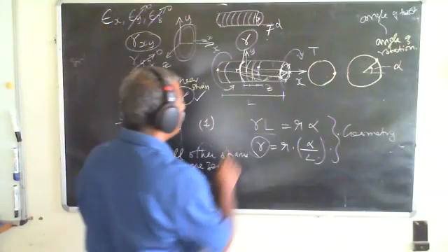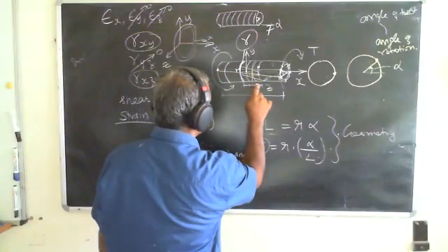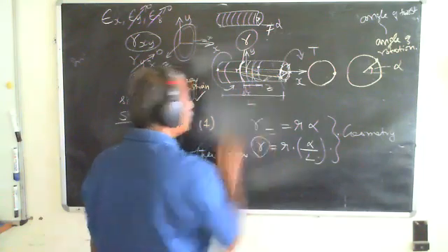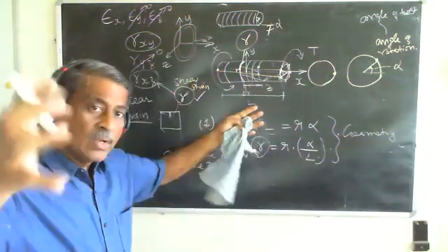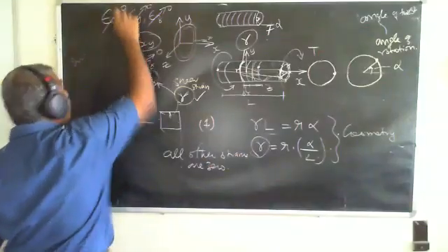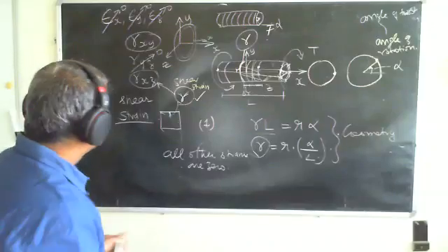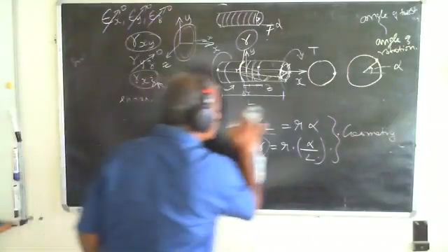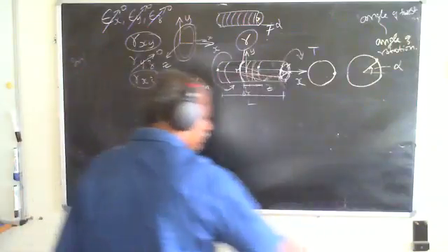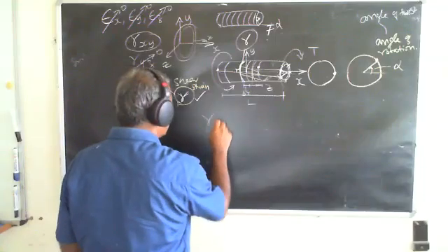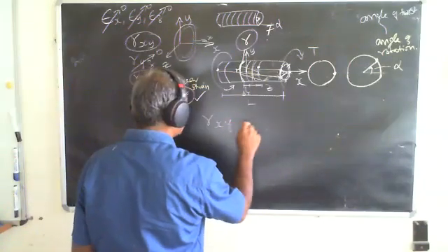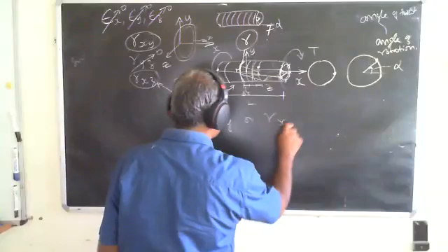But what we found is that this individual length, which is delta x, remains delta x, which means there is no elongation that has occurred in the x direction. So this also goes to 0. This implies that I may have only gamma xy or gamma xz.